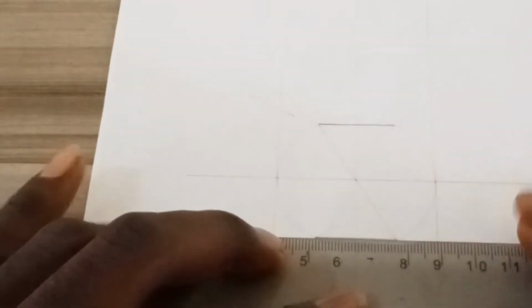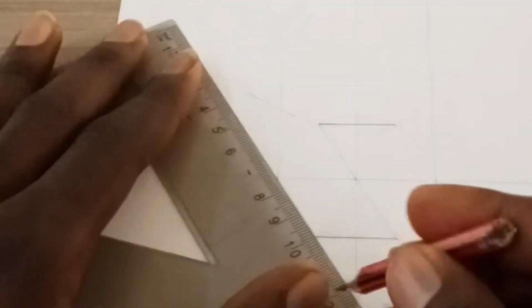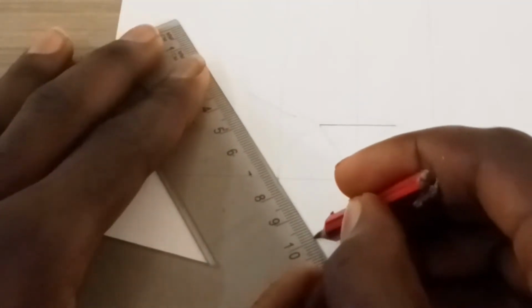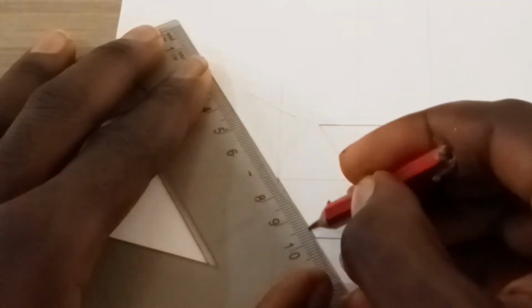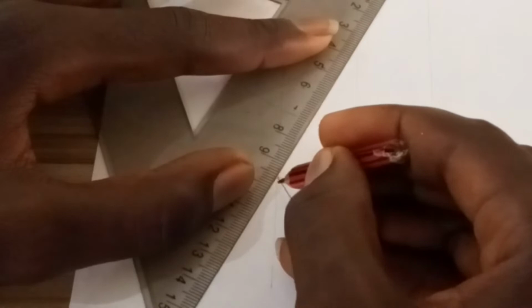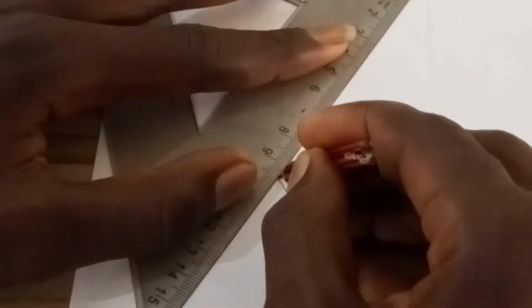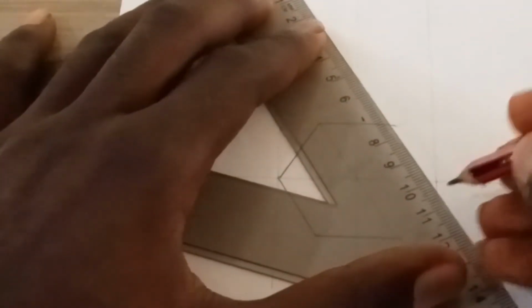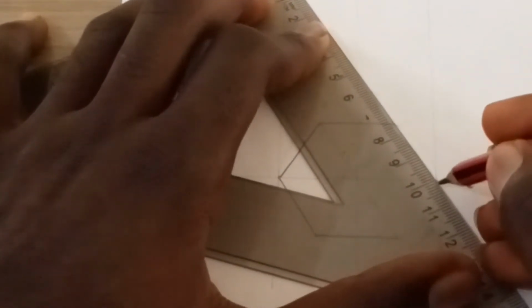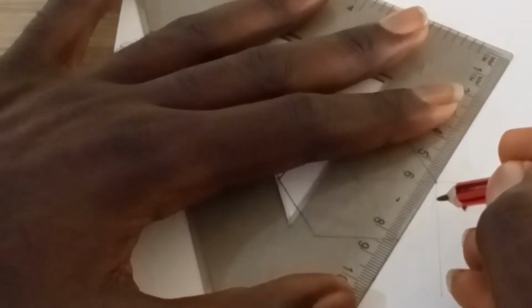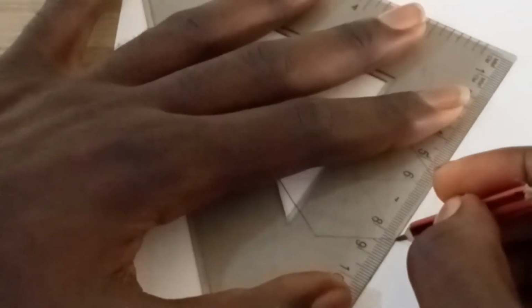Our hexagonal pyramid, as we saw earlier, has a triangle for the front elevation and a hexagon for the plan. So the plan of a hexagonal pyramid is a hexagon, while the front elevation is a triangle. The triangle and the hexagon have to be drawn with thick continuous lines. That's why I'm drawing my hexagon with a thick continuous line, and my circle was initially drawn with a thin line because it's only a construction needed to get our hexagon.